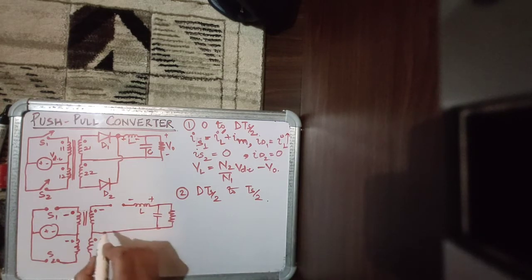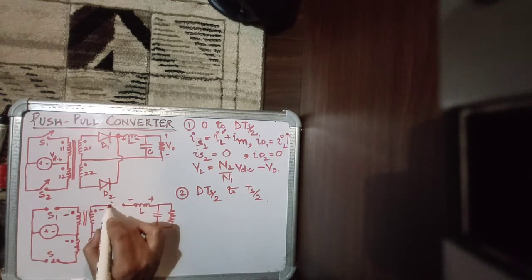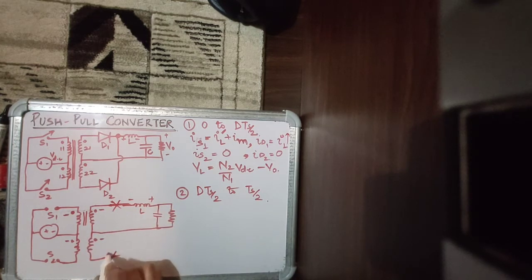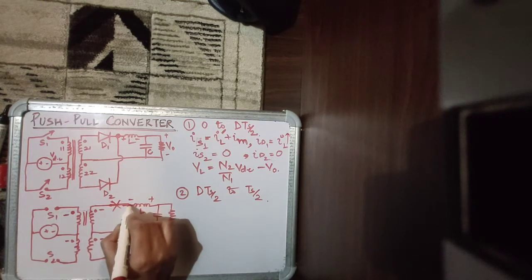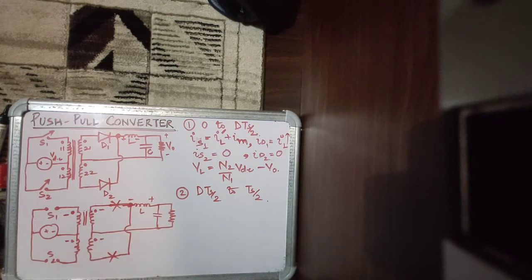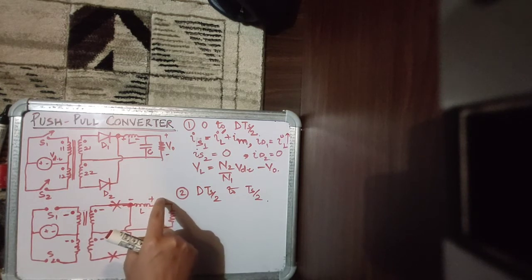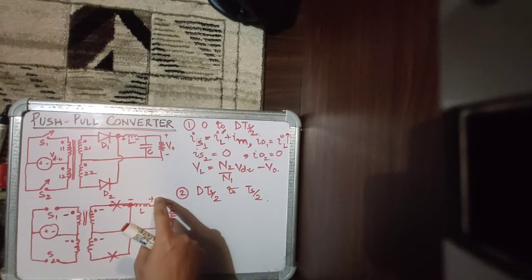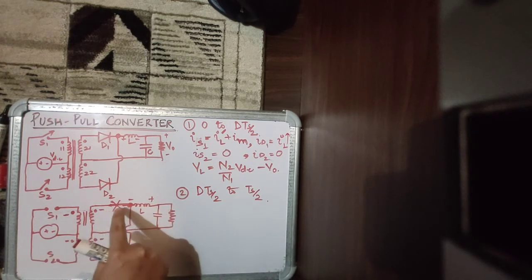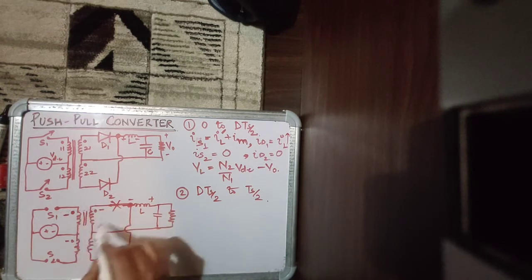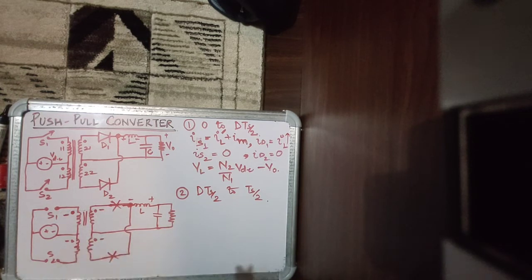One is this diode itself, and the other is this plus sign forward biasing this diode also, and then going on like this. Because your inductor voltage has switched, this potential becomes a high, positive potential point, and it forward biases this diode as well as this diode by overcoming the potential at the windings itself.